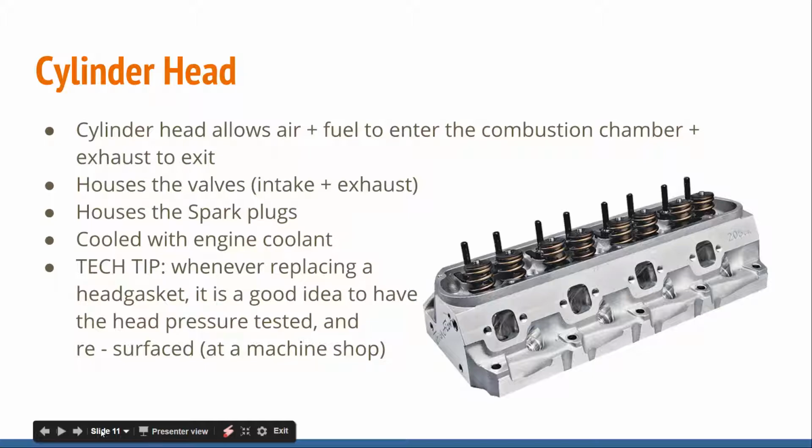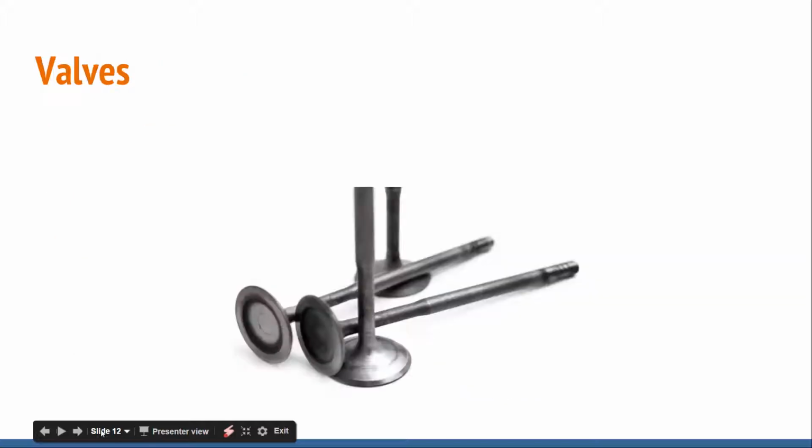just to err on the side of precaution, we usually take the cylinder heads, bring them to the machine shop. They're going to do a couple tests on them, a pressure test, a vac test, tests all the valves, and it also checks for any sort of hairline cracks in the cylinder head. And then they also resurface the gasket surface, the mating surface. They clean it up, flatten it out. So that's always a good idea when you have heads off. It's not real expensive, and it's going to save you a possible comeback.